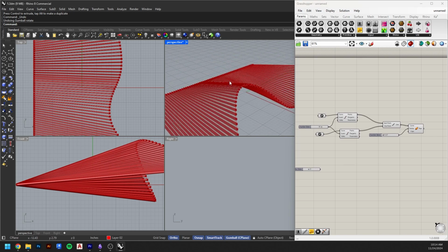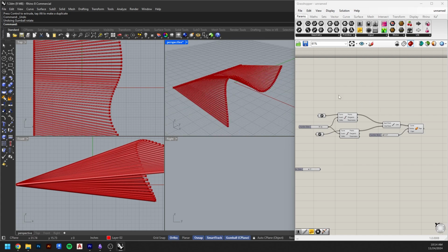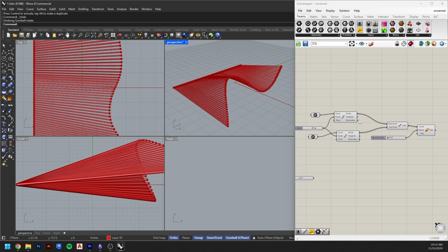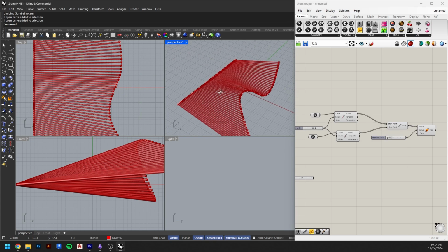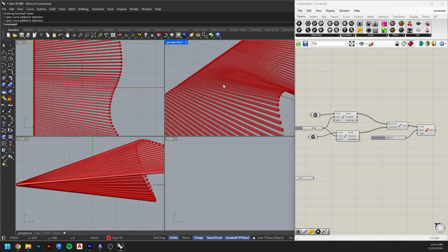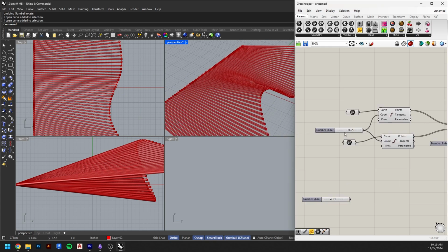But here's what I want you to think about. When you decide to use Grasshopper on your project, you have to make sure that you're using it in a smart way and in an efficient way, because Grasshopper is not Rhino, okay? You don't want to start building stuff in Grasshopper. You build stuff in Rhino. You build your objects, you build your final building in Rhino. But Grasshopper is just about building logic. It's just about building the arrangement of lines and lines between lines and the skeleton that objects are going to sit on, okay?